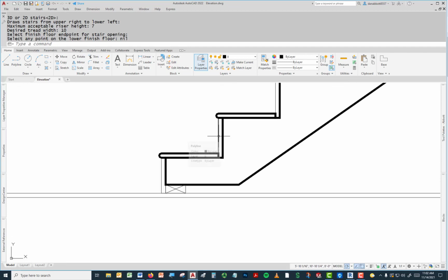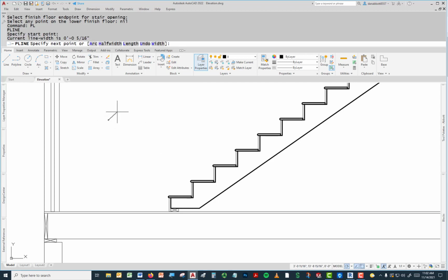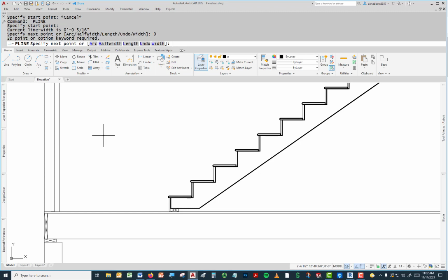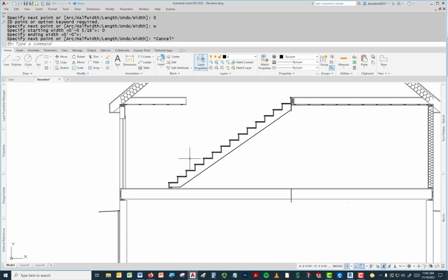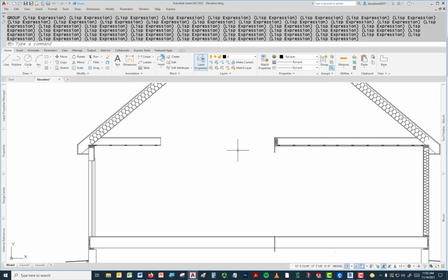It also has a series of polylines, and the reason those are so thick is because I probably drew a polyline one time, and I used a starting width and an ending width, which is exactly what I did. If the width had been set to 0 the last time I'd done a P-line, and then I did the stairs, we'll just go back and undo those now. In fact, you can undo it in one step.